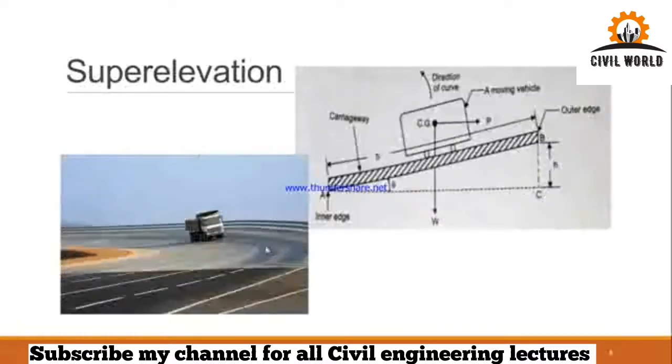Here you can see this is the inner edge and this is the outer edge. The elevation of the outer edge is higher as compared to the elevation of the inner edge, and the rise of the outer edge as compared to the inner edge, or the inward tilt provided in the cross section of the road in a horizontal curve, is called superelevation.